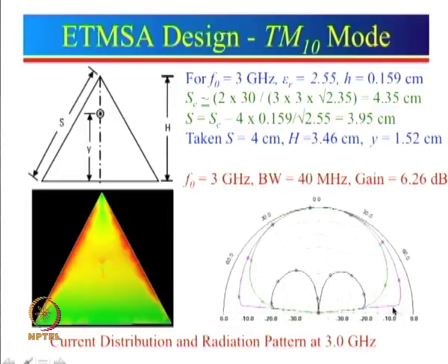When we take an infinite ground plane with infinite dielectric, this boundary condition does not get satisfied in their software. That software always gives a wrong value along theta equal to 90 degree. So, in reality I just want to tell you that this value goes over here. However, in I3D if you use a finite ground plane as well as a finite substrate, this error will not be there.